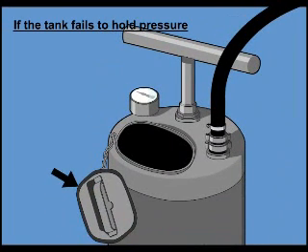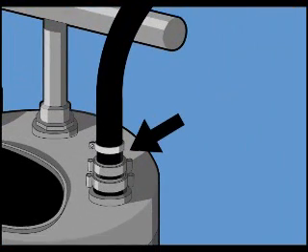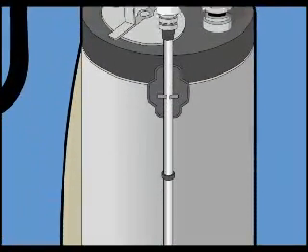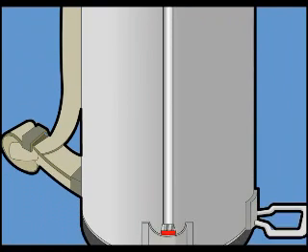If the tank fails to hold pressure, check the rubber seal on the lid and replace if necessary. Check the hose connections to the tank are tight. Check the relief valve is seated correctly to avoid loss of pressure.